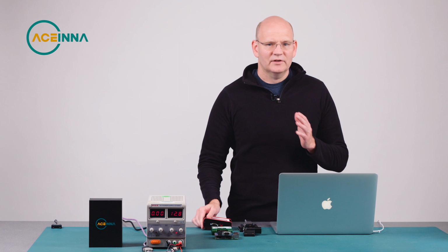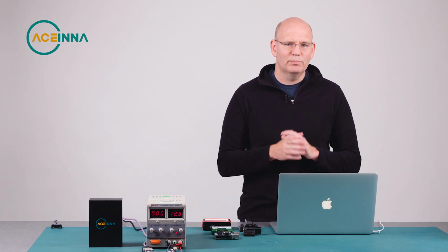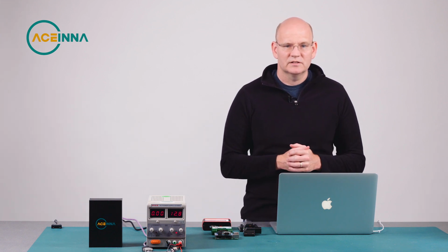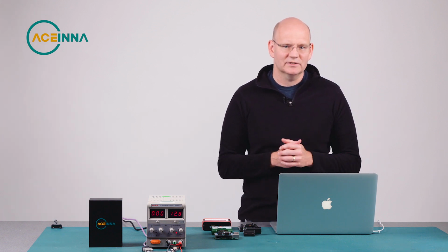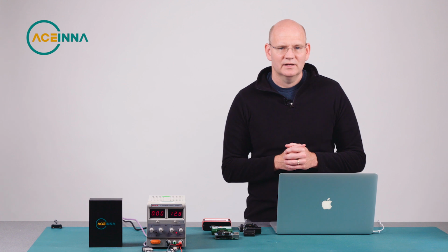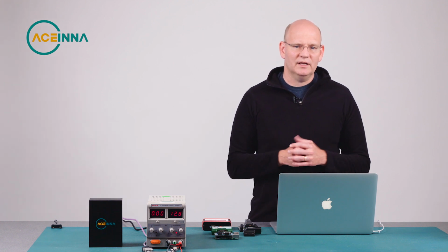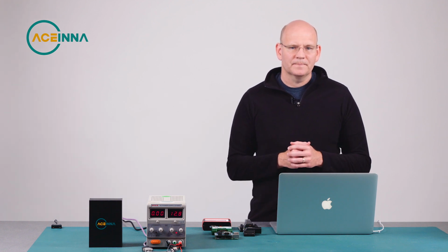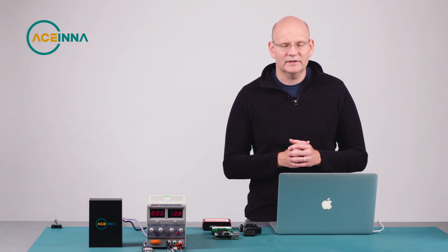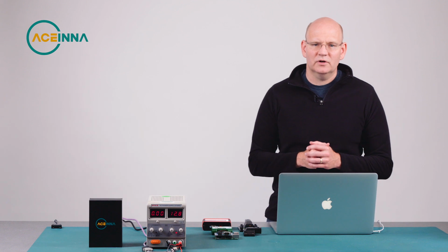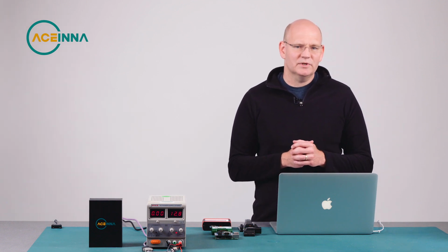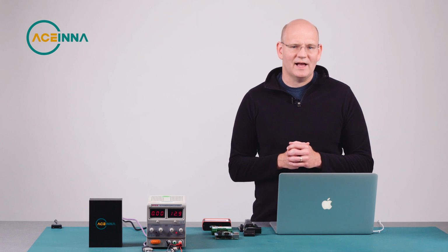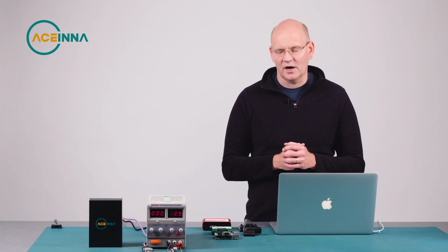Now that we have some analyzer options, let's go ahead and build an IMU application. Since many automobiles use CAN 2.0A with 11-bit IDs, we will start with this case. CAN messages are available over the OBD2 port, but this messaging is not globally standardized. To get a feel for what these messages look like, we can turn to the open source OpenDBC project, which declares its mission to democratize access to the decoder ring of your car.